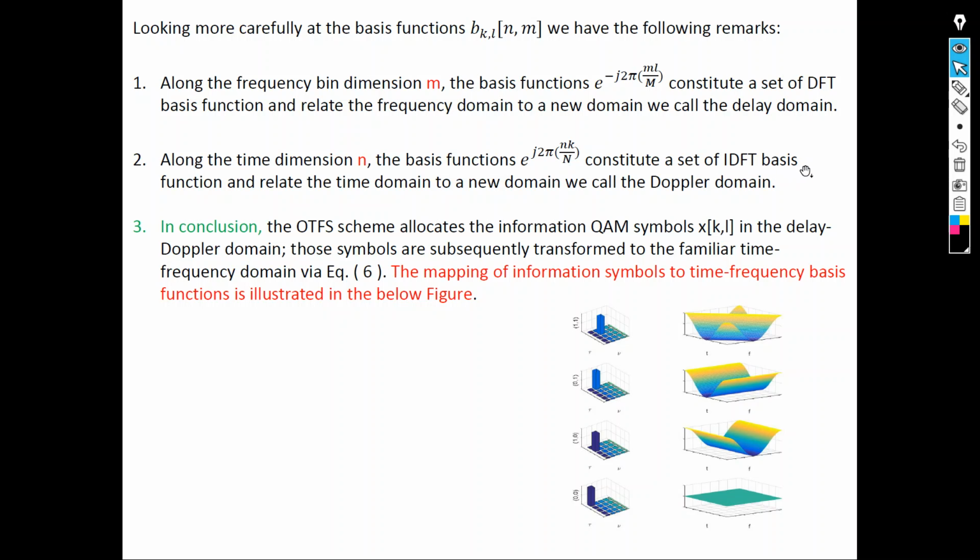Constitute a set of IDFT basis functions and relate the time domain to a new domain. We call it the Doppler domain. In conclusion, the OTFS scheme allocates the information QAM symbols that are located in the delay-Doppler domain to the time-frequency domain via a mapping process. The mapping of information symbols to time-frequency basis functions is illustrated in the following figure.